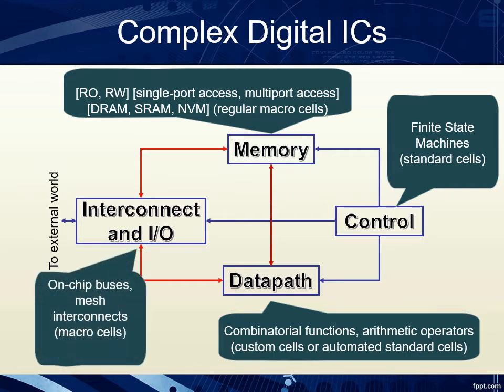Finally, we have the input-output circuits. We need specific components which are buses and interconnects and are typically macrocells. Macrocells mean they are larger components and very specific for this type of application. Since input-output circuits communicate to the outside world, silicon chips should have larger drive currents because outside the chip everything is larger. Larger capacitances, larger currents. So the blocks must be able to cope with that type of circuit.